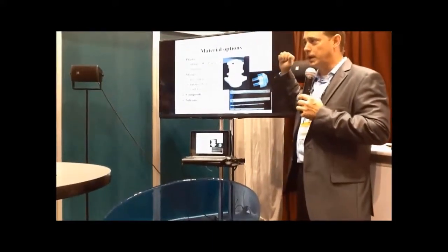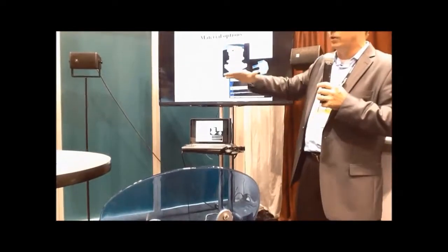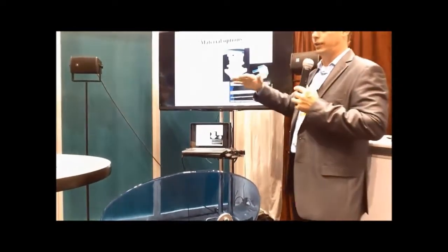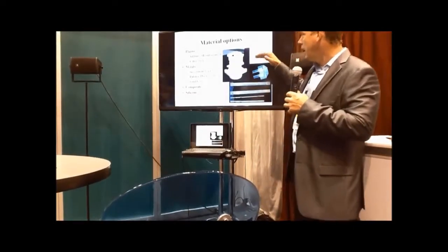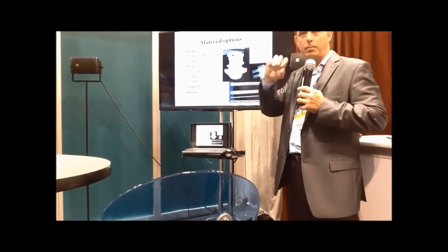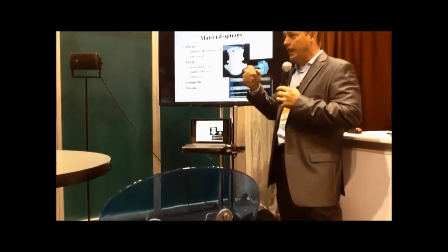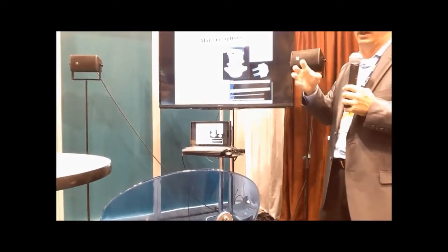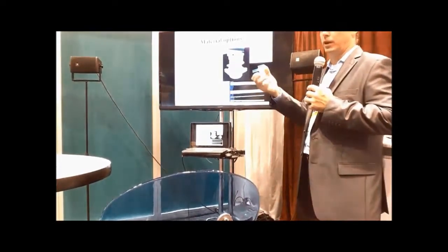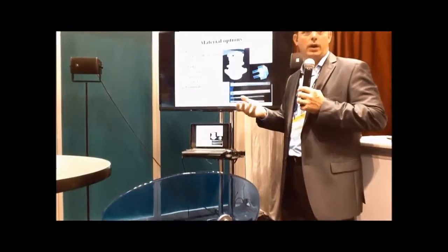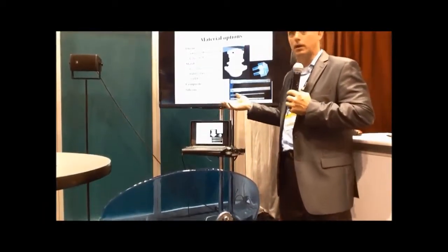One of them in North Lake up here is actually printing the binder onto a sheet of Kevlar or composite, and there's another material I can't think of. They're taking and stacking these and then putting them into an oven. When it comes out, they're blasting away the area where the composite material does not have any of the binder. So now you end up with a 3D printed composite part.